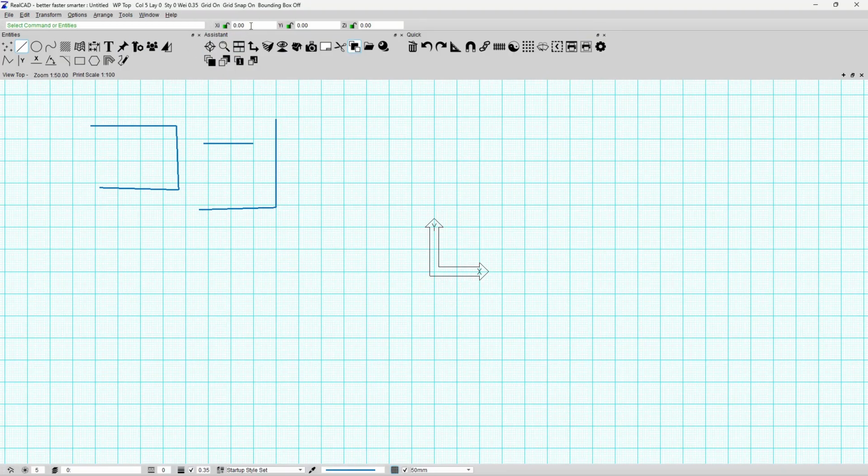To the right is the coordinates bar. Again, it's a separate floatable dockable menu, and it's where you would enter values in the X direction, left and right, the Y direction, up and down, and if you're working in 3D, the Z direction, which would be towards you or further away from you. Items such as the padlock can be clicked on and locked into position, locking the value that you've typed in, or unlocked, or simply by pressing P on the keyboard, you'd also be able to lock or unlock. If we were in the Y coordinate section and I pressed P again, it would lock or unlock whatever value I had typed in here, and so on.